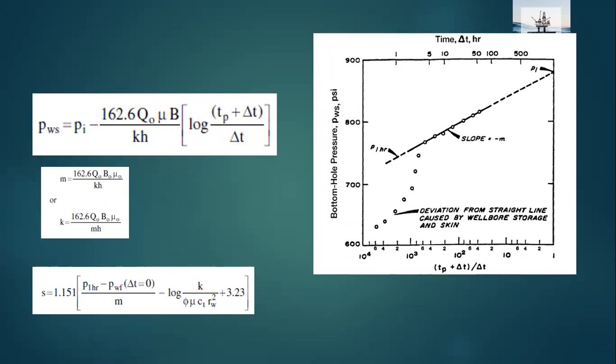This pressure rises by the movement of fluid, where the fluid starts to move towards your well. Once the fluid starts to move from the reservoir towards your well, it will start influencing the skin zone, which is near the wellbore. This will take around 1 hour. So fluids will move until they reach the well.